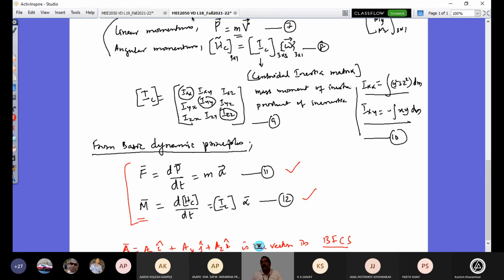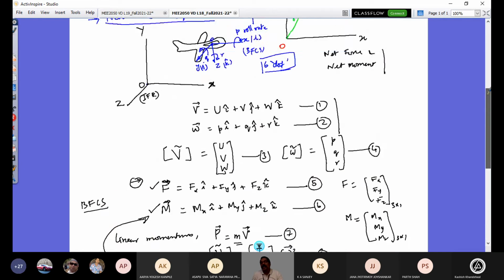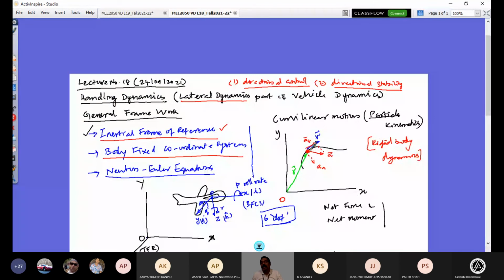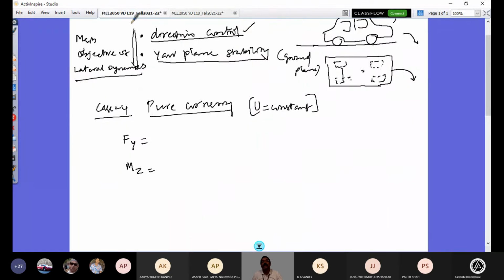You see here. What have we seen here? This velocity can be constant, and you have AT and AN. So AT is 0, but AN is necessary to have the course maintained by the vehicle, and that is taken care of by Fy. So you'll have a lateral acceleration, but not the longitudinal acceleration component. That's the meaning of this, and then the cornering is called pure cornering.